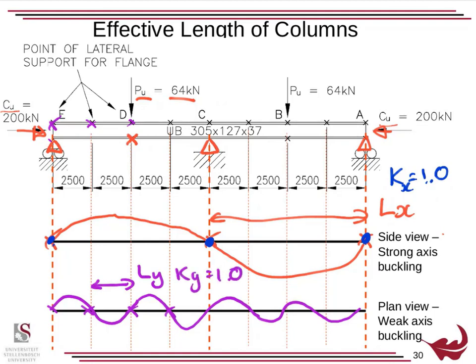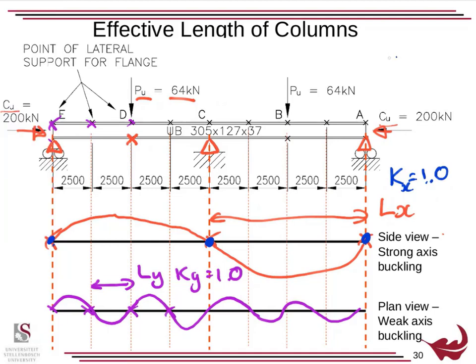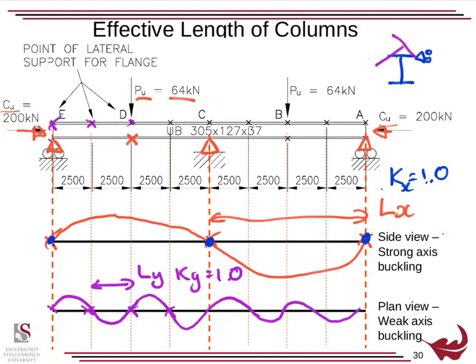Now, what about torsion? What is torsion? Firstly, hopefully you all know by this stage, but you've got a beam. If I have a support there and there to it, I've got a floor fixed to the top and a beam to the bottom, or I've got a beam connected into the side of it which prevents twist. You don't need very much. If you just have, for instance, 2 little bolts, you'll prevent torsion. Now, this will have a torsional restraint. This won't. So when I have a look at this, this will now rotate like that.